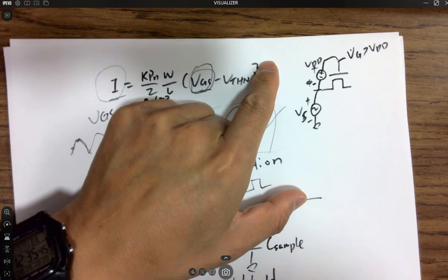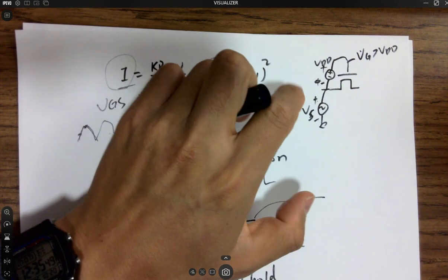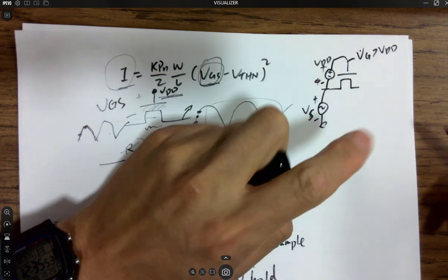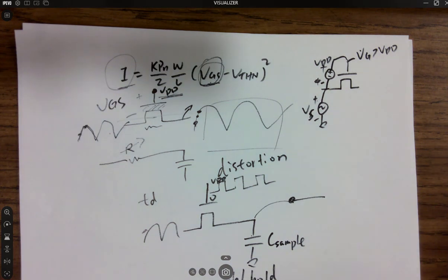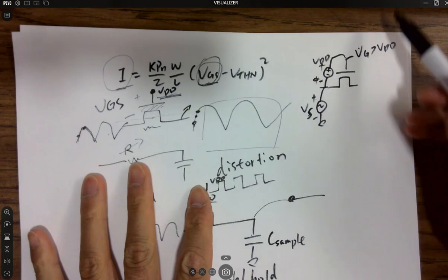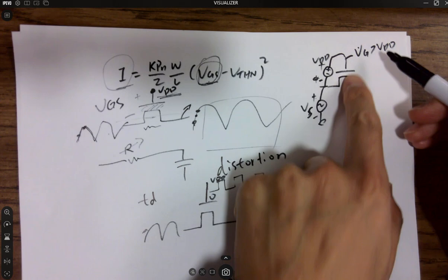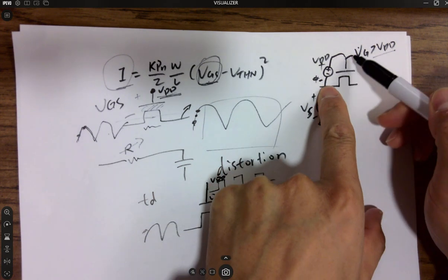Okay. However, the largest voltage available on the circuit is usually just VDD as a digital circuit. How could you create a voltage which is larger than VDD? So yeah, you need a charge pump to create that. So that's why we are talking about charge pumps. We'll get into that pretty soon. But now you can see that because I tied, even though VG is larger than VDD, VGS is not changing.